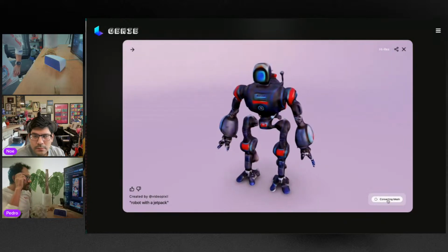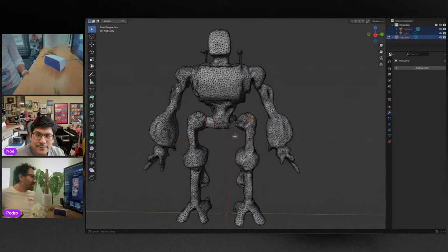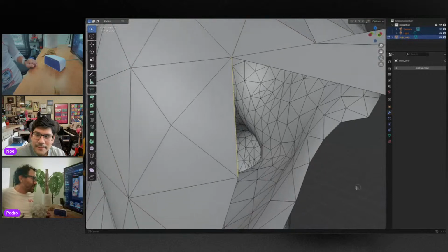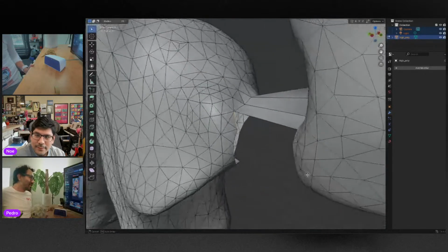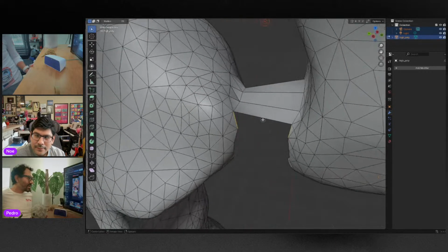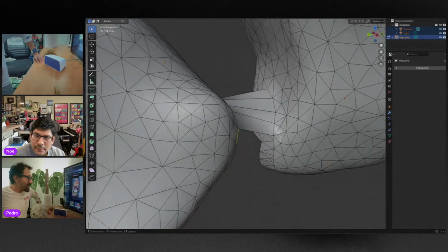This is really cool. And so we wanted to see what the mesh that it generates looks like. And yeah, it couldn't even join the leg to the torso. So of course, we go back into Blender and you can go in there and join the faces. I'm just bridging the edges between that. And one of the things that I like about this segment is it forces me to go in there and learn Blender.